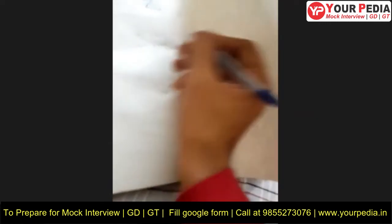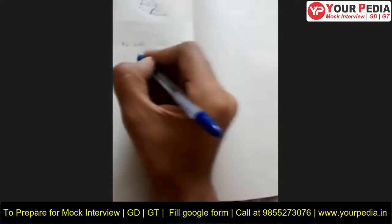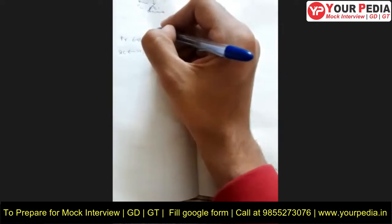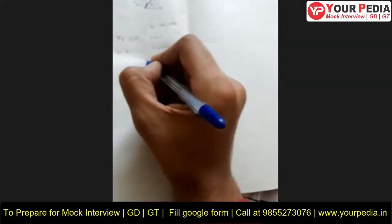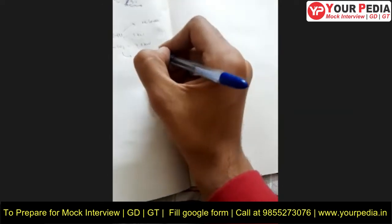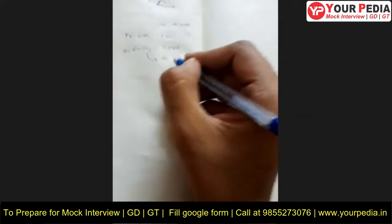Okay, sir. Wattmeter one is connected to the primaries of both transformers. This one is connected to the secondaries of both transformers. Wattmeter one will give no load losses, sir, whereas wattmeter 2, which is connected to secondaries, will give copper losses, sir, which depend on current.